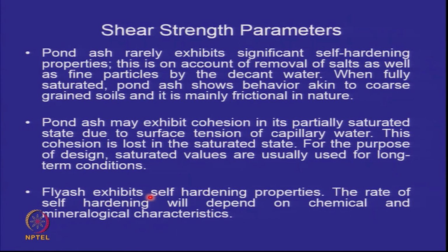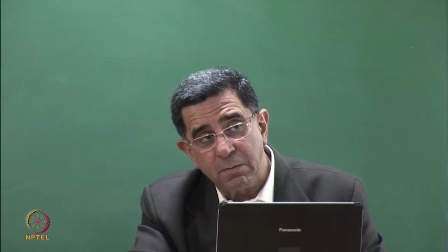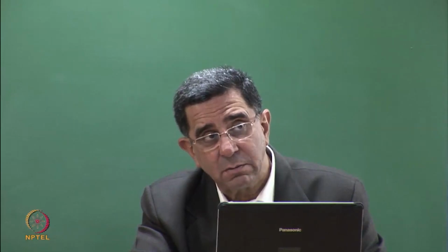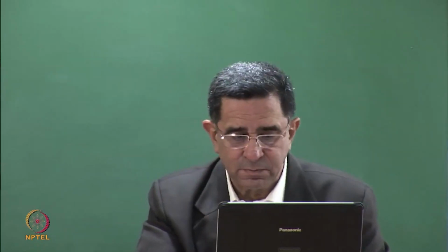Fly ash will exhibit self-hardening properties, but it will depend on whether you have collected it in the dry state or not. And this is the most valuable thing from the perspective of people wanting to use the ash in cement. So you will always find cement companies will be very interested in your fine portion of the fly ash and not so interested in the coarse portion of the fly ash.